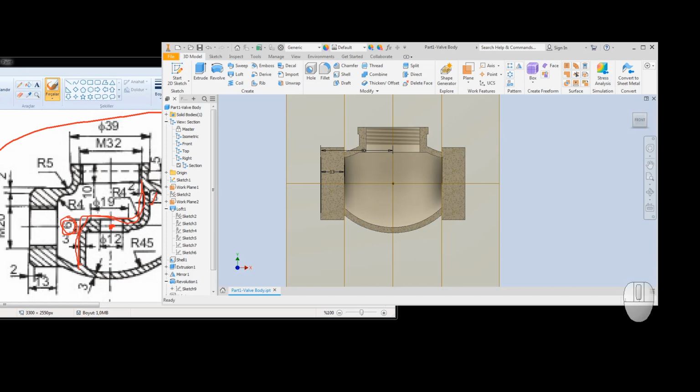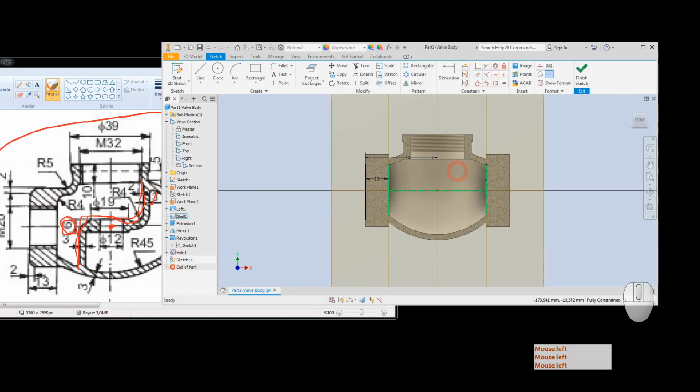I have previously created some files here at this point. For this, I will just overwrite. Save again. This warning just comes from the half section view because we haven't saved our half section view under the view menu.